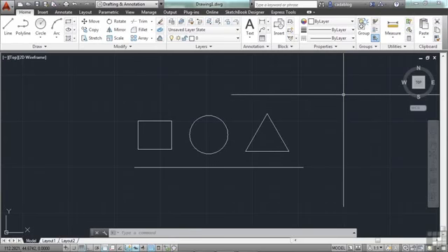In the previous section, we discussed the value of inputting commands with the keyboard. One key to efficiency in AutoCAD is taking advantage of keyboard shortcuts, or command aliases, and also the function keys. Let's look at the function keys first. They work like toggles. They turn certain drawing aids on and off. The two you're going to use the most will be the F3 key and the F8 key.